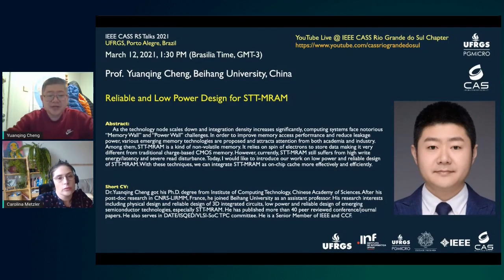For this one, usually we do not use PMOS transistors. We use NMOS transistors in our MTJ structure, because usually the electron mobility is much better than the hole mobility. That's why the NMOS transistor can deliver larger current compared to the PMOS transistor.